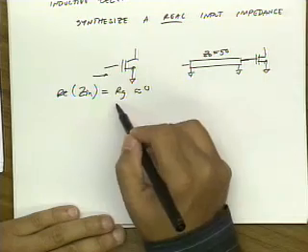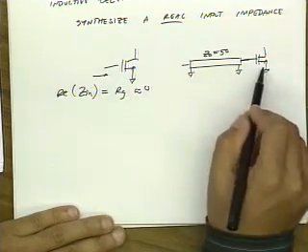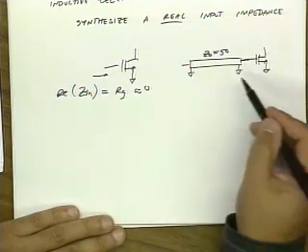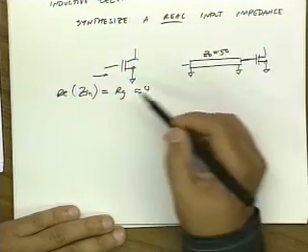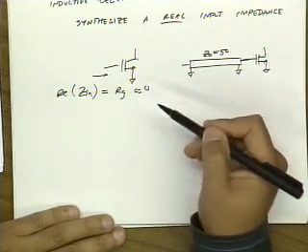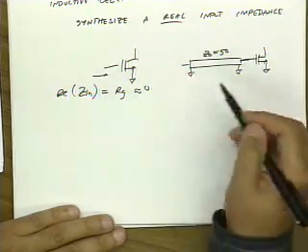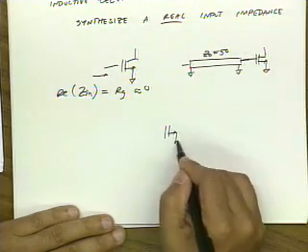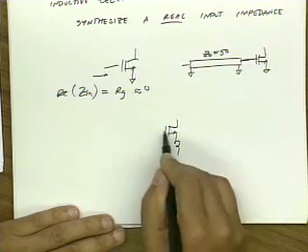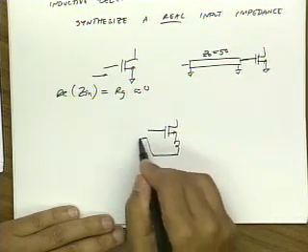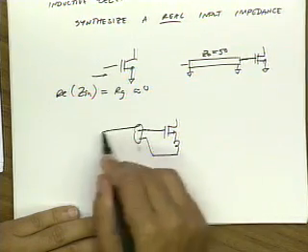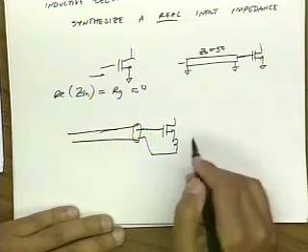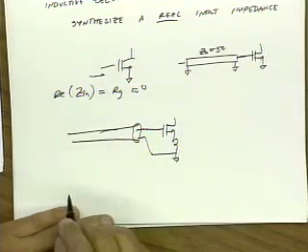Well, Rg is the real part of the input impedance, which is very small. It might not be possible to drive it with a source that has such a small, let's say this is 1 ohm, it might not be possible to drive it with a 1 ohm source. So inductive degeneration lets you raise the input impedance to any value that you want.